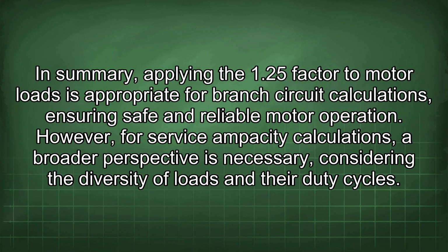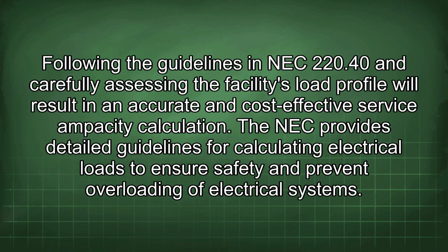In summary, applying the 1.25 factor to motor loads is appropriate for branch circuit calculations, ensuring safe and reliable motor operation. However, for service ampacity calculations, a broader perspective is necessary, considering the diversity of loads and their duty cycles. Following the guidelines in NEC 220.3B and carefully assessing the facility's load profile will result in an accurate and cost-effective